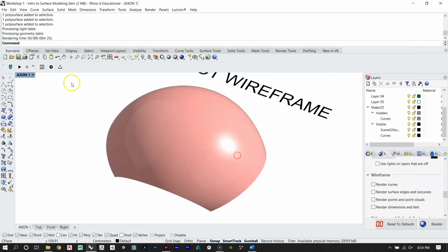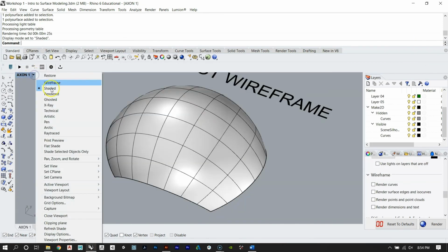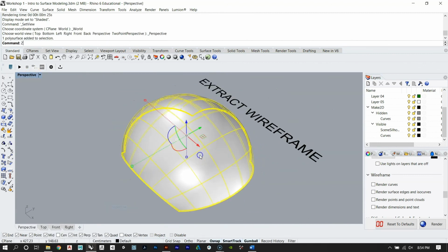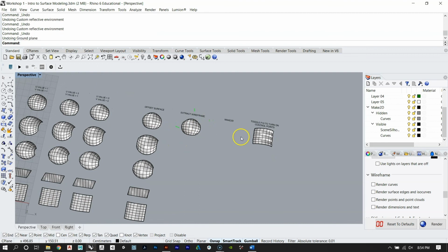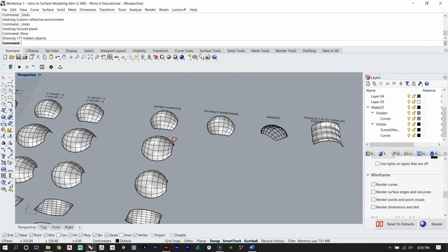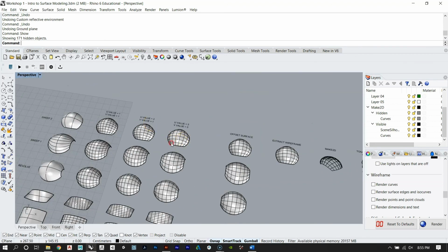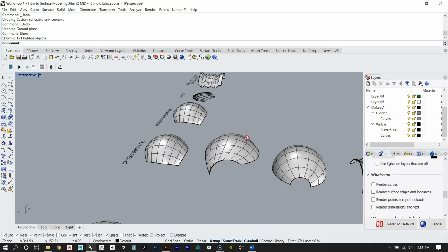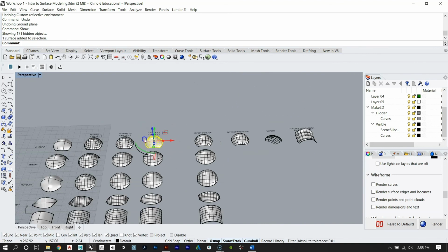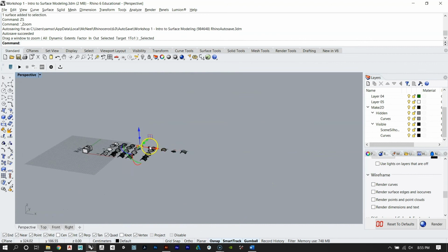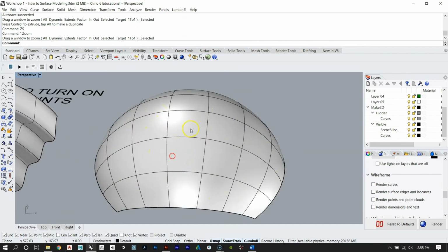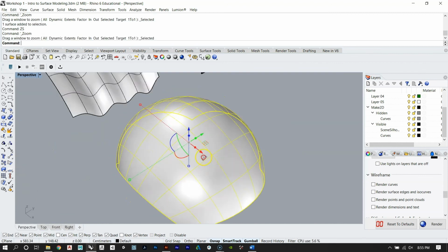The last thing I'm going to go through for this tutorial, I'm just going to switch myself back to perspective. Is more free-form modeling. Okay, so you would do this before you thicken your surface. So if I just have an open surface, something like this, okay, I'm going to pull this over, and I've already started to kind of modify it.